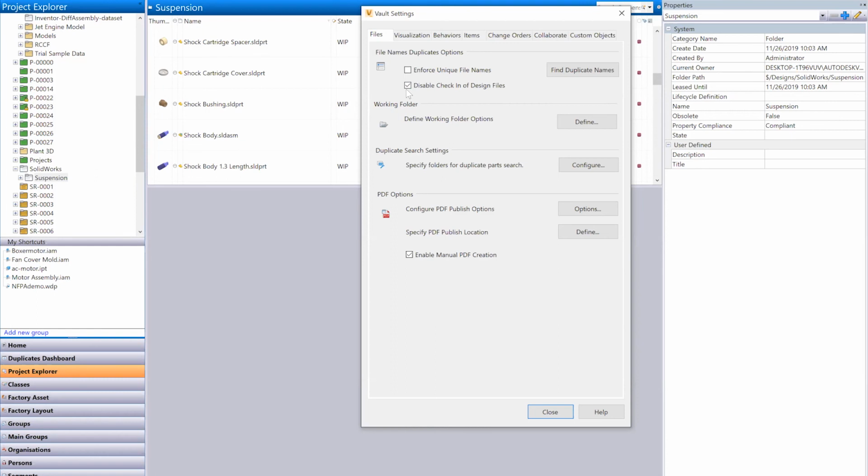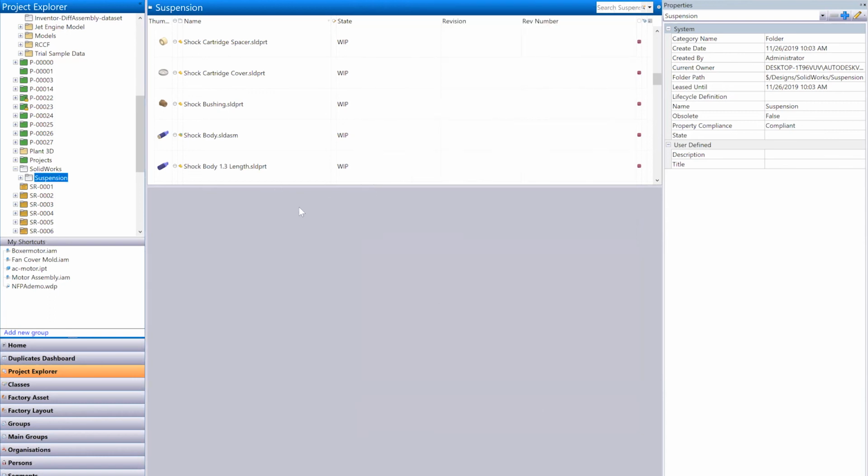This setting prevents you from dragging and dropping a CAD file into Vault. So if I were to grab my SolidWorks assembly and just drag and drop it into the Vault, Vault wouldn't know or understand what the relationships of those files are. Vault gets that information specifically from the add-in. And as Jose has walked you through today, that's done by either using the task manager check-in or checking the files in via the add-in or the authoring tool.